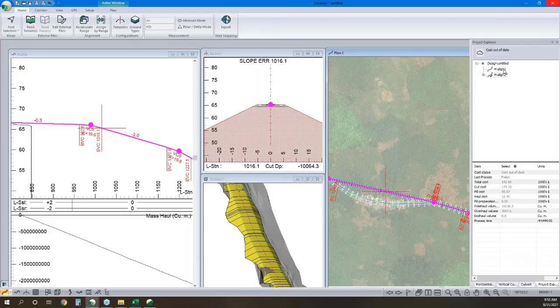So if you design two alignments by hand and you just happen to do a better job at designing one of the alignments, it can often influence which one's best, and then you spend a bunch of time chasing down the alignment that actually wasn't the best alignment, because if you optimize them, you could have actually gotten the cheapest cost, and that difference between a good by-hand design and an optimized design can influence which one's the better solution.